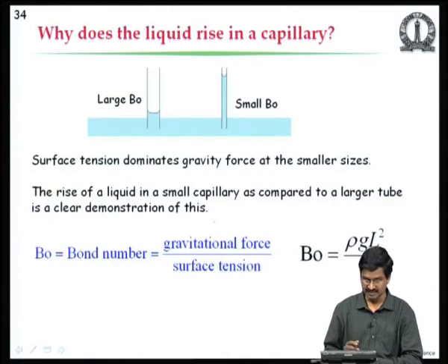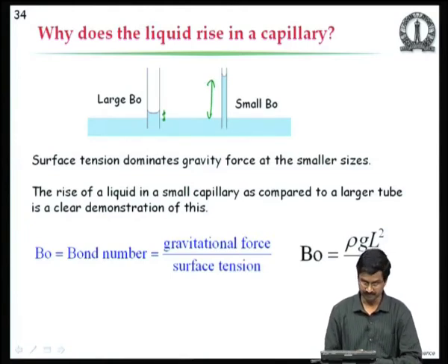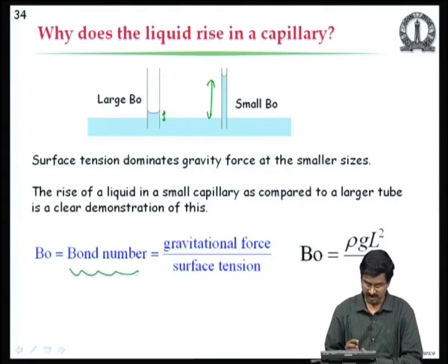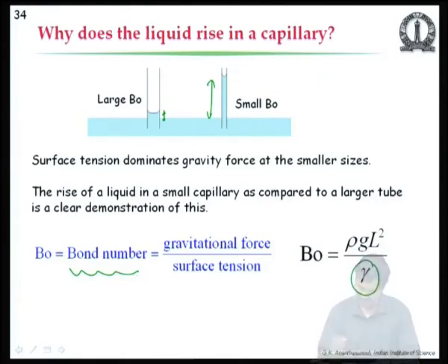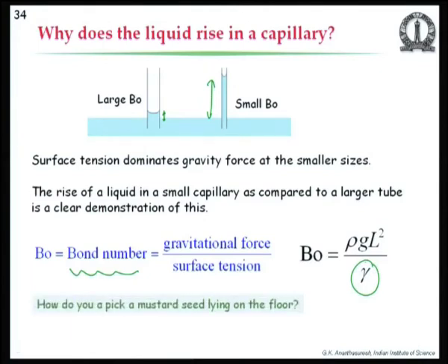And in capillaries, when things rise in a small tube, the liquid will rise to a higher height than in a bulky tube, again a consequence of sizing or scaling, where we have another non-dimensional number called Bond number, which is the ratio of gravitational force to surface tension. If surface tension is high, then the Bond number will be lower, and the scaling effect becomes not so important, but the surface tension related forces dominate at the micro scale. So, you can actually make things move using surface tension.